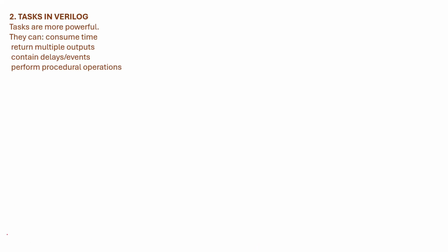Previously functions were not allowing @(posedge clock) and all these things, right? Now posedge clock, wait conditions and delays are all allowed in the task. And one thing: a function can call only a function, it cannot call a task, but a task can call functions as well as tasks. Suppose you have written an add function.